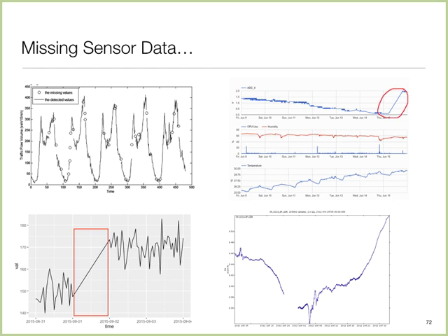If you think about it, we use inertial sensors with 9 channels: 3 accelerometer, 3 gyro, and 3 magnetometer. But we only have 6 degrees of freedom, so clearly we have redundancy. Something can be computed from something else, so it ought to be possible that if some channel is missing, I can fill it in with other channels.